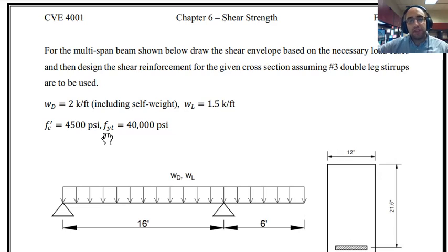So the first step is to understand the amount of shear force demand that we have on the beam, and for understanding that we need to draw the shear force envelope, and shear force envelope is different than shear diagram.